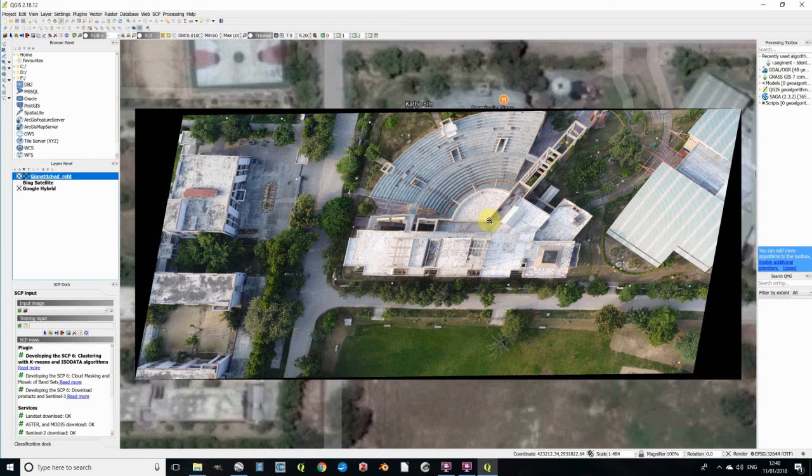Now, you could, however, improve the quality of this by adding maybe 5 to 10 more control points, and then the things would average out to be approximately correct. So if all you need is a 2D map, I guess you could consider doing it this way, but this is a valuable exercise in that it shows why it is important when you've got large variations of topography, especially in urban settings where you can actually have a building which is 20 meters higher than its neighboring ground. You've got very big altitude variations in local areas.